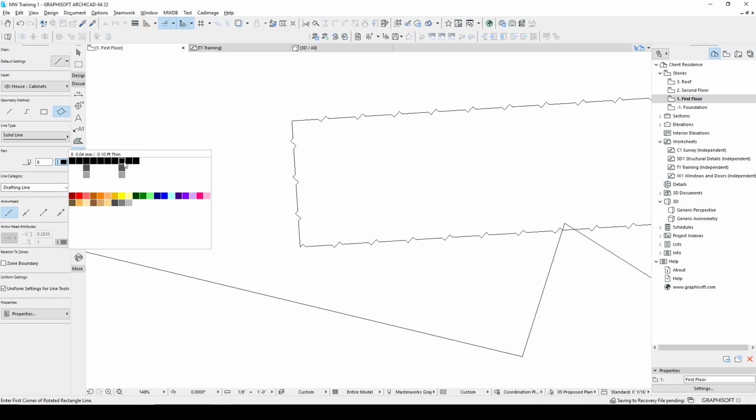And so they're also labeled what type of pen they are: objects, setbacks, contours, fills, cuts, so that I can try to use these pens as consistently as possible. Now what I do is, these pens moving down are the same weight, but different halftones. And you can have halftone for any of these. I just do a couple. Again, if I have too many choices, it's just too hard to enforce any standards. These are what I use for my fills for my 2D shapes, my hatches, if you're from an AutoCAD background.